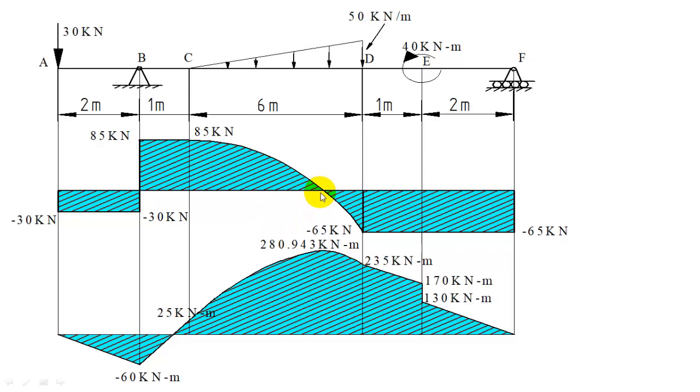But we have understood that there is a peak because shear force is changing its sign. All these calculations are required because shear force has changed its sign. If shear force was not changing its sign under UVL, the problem would have become very simple. You can plot it by cubic variation without a peak. But in this case, the bending moment is going to be a cubic variation with a peak coming under this point where shear force is 0.